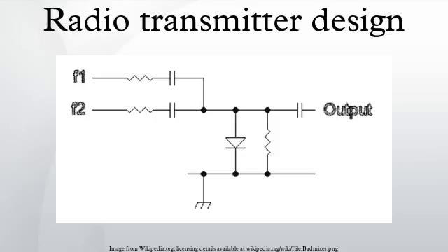The use of PDM switching regulators makes this system very efficient, whereas the original analog regulators were very inefficient and also non-linear. Series PDM modulators are used in solid-state transmitters also, but the circuits are somewhat more complex, using push-pull or bridge circuits for the RF section. These simplified diagrams omit such details as filament, screen and grid bias supplies, and the screen and cathode connections to RF ground.